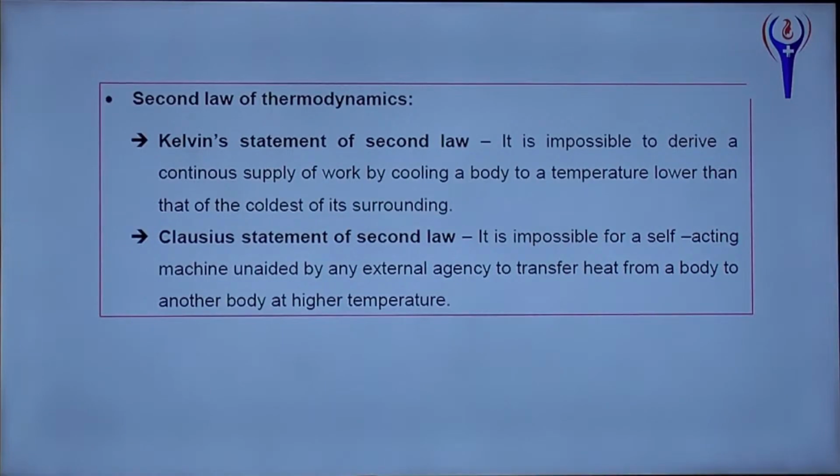Here we are doing some external work, the compressing motor work, such that it can transfer heat energy from inside the refrigerator to the outside. If you go to the back side of the refrigerator, you may feel hot. It continuously transfers heat energy from inside to outside. By itself, is it possible? Not possible. That is the Kelvin statement.